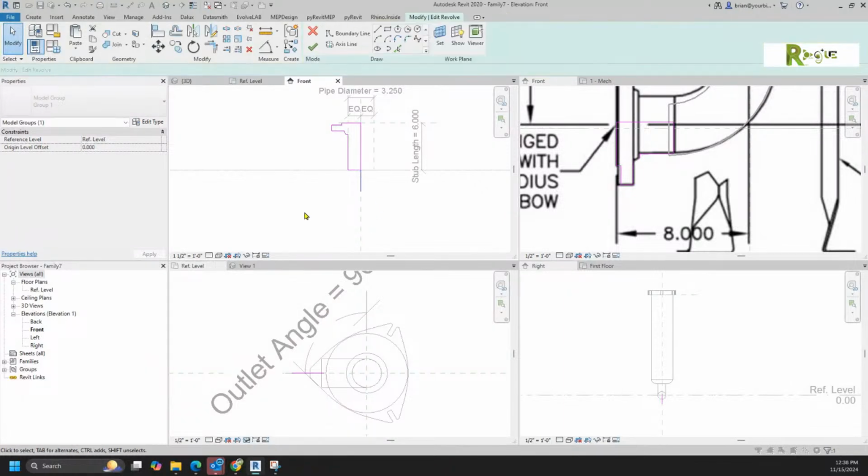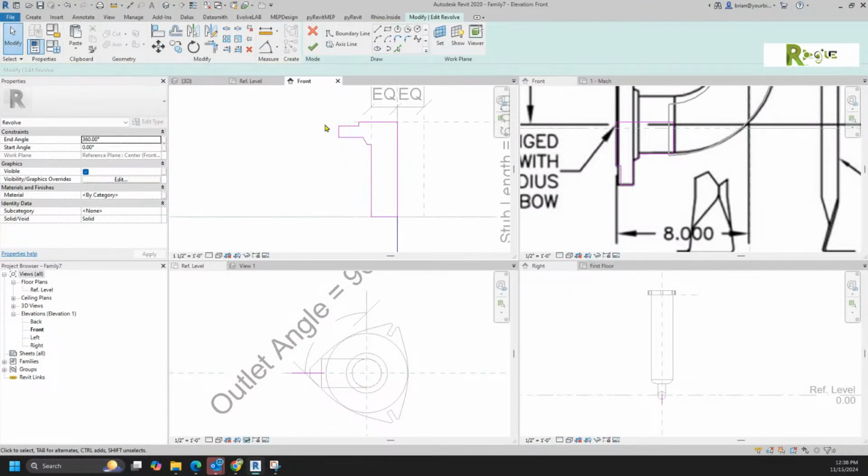Now, if Mike said, well, I'm worried about this distance of the flange actually gets bigger, we could put extra dimensions in there. I just challenge you to keep it very simple, just a couple parameters to make your adjustment. Because if you've ever gone in and tried to fix someone's family or work on someone else's family, when there's too many parameters, it makes the family next to worthless, right? Correct.